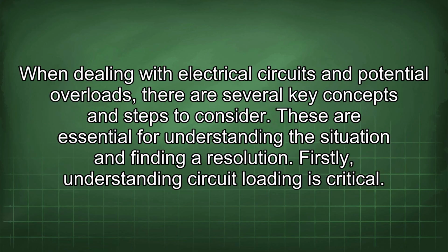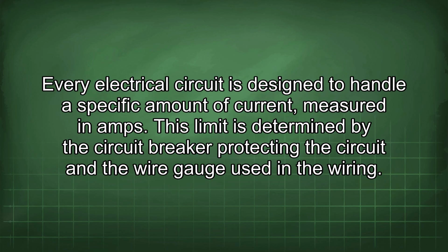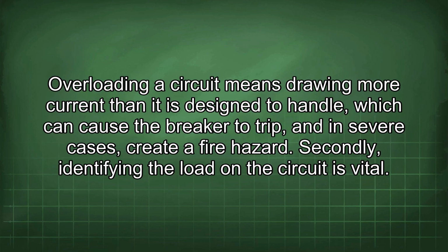When dealing with electrical circuits and potential overloads, there are several key concepts and steps to consider. These are essential for understanding the situation and finding a resolution. Firstly, understanding circuit loading is critical. Every electrical circuit is designed to handle a specific amount of current, measured in amps. This limit is determined by the circuit breaker protecting the circuit and the wire gauge used in the wiring. Overloading a circuit means drawing more current than it is designed to handle, which can cause the breaker to trip, and in severe cases create a fire hazard.